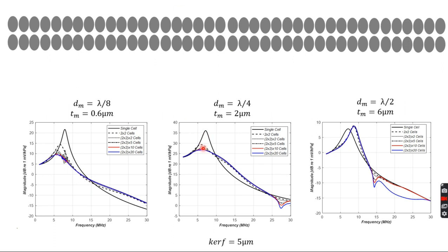I mean, the peak sensitivity is better than in all the other cases for quarter wavelength diameter membranes. You see that it's higher than both of these cases. The frequency doesn't shift, because the frequency shifts for smaller aperture sizes a little bit to the left and then right for the larger aperture sizes. Smaller aperture sizes are more affected by the mutual crosstalk, while the larger aperture sizes are not much affected, but the stop bandwidth is much less as compared to 28 megahertz.